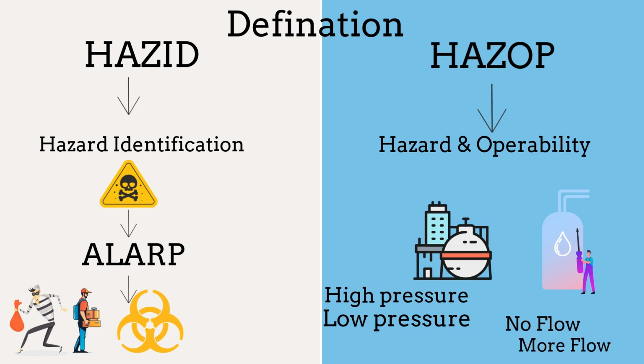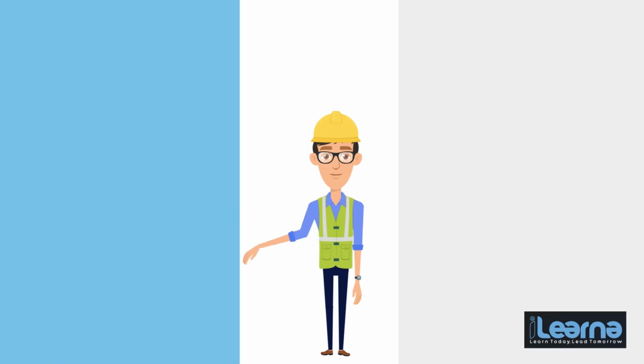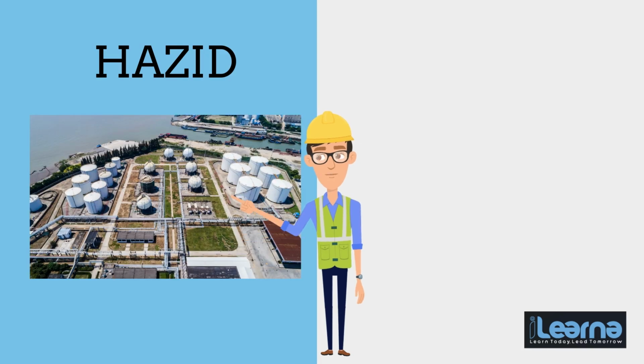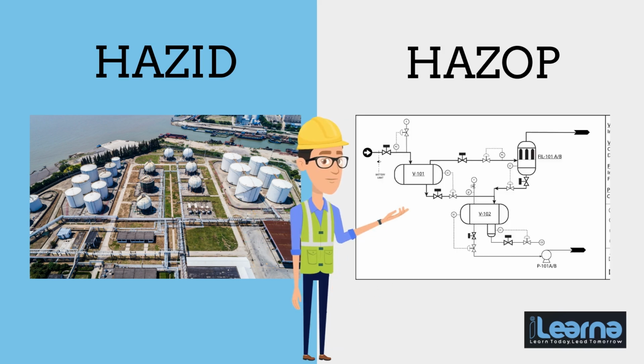Now, let's discuss the scope and level of detail for each study. HAZID provides a general or helicopter view of the plant. It considers potential risks at the plant level and evaluates the relevant safeguards in place. In contrast, HAZOP is a more detailed design verification study. It focuses on potential risks at the level of individual equipment or process nodes, along with their specific safeguards.